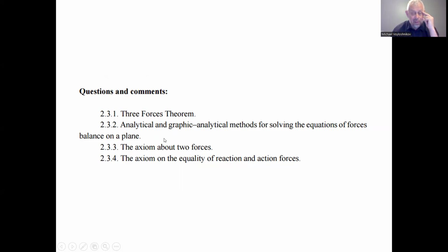For the graphic analytical, we have to do the polygon as a consequent addition of each of the forces acting on the mechanical system. For three forces, the polygon will be a triangle of vector forces, and after the geometric mathematical transforms of these forces within the polygon, we can find any unknown vectors and force magnitudes